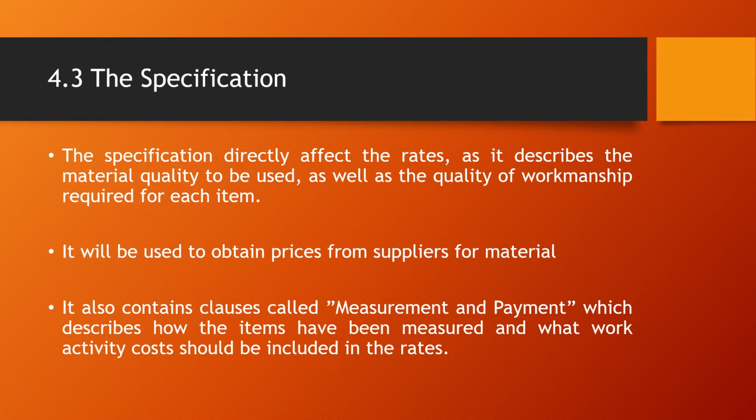So that means that you have to put a certain amount of material, compact to 90%, and then put the next 300 layer, compact to 90%. Now, if you don't compact to the required compaction density, when they do the test and find that you are falling shy of that 90%, they could say, you know what, strip this whole trench and recompact, so that you can achieve 90% compaction.